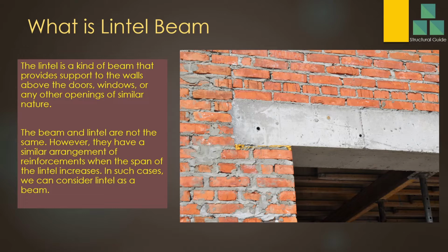What is a lintel beam? A lintel is a kind of beam that provides support to the walls above doors, windows, or any other opening of a similar nature. You can see the lintel in this figure. This lintel supports the brick wall above, and it rests on the brick wall. Now this is a lintel.